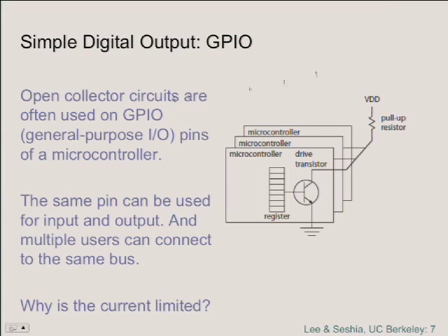The way you put the value onto the data bus is by turning on a bunch of transistors that are connected to the lines on the data bus. And hopefully, if that address 20 is put on the address line, nobody else on that bus will respond to it because nobody else responds to address 20. So if you're the only one responding to address 20, you can safely assert your data on the data lines, and your value will be then visible on the data bus.